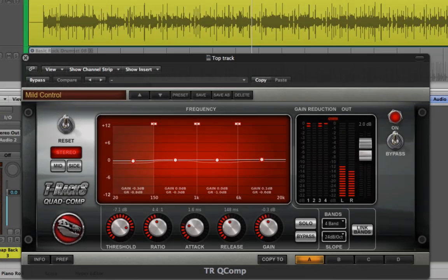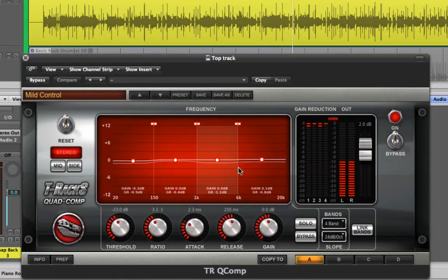Multiband processors let you split the signal into a number of frequency bands. In the case of the Quad series, 4 bands, except for the De-Esser, which is 3, and they let you separately apply the processing to each band. This allows for more precise processing in situations where you want to affect a defined part of the signal, but not all of it. So why multiband compression?